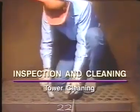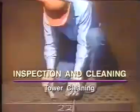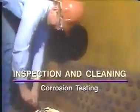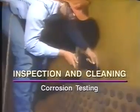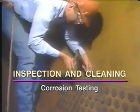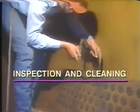Even after purging and water flooding, there are usually some stubborn deposits that remain in the column. These deposits are removed with special solvents or by manual scraping. After the tower has been thoroughly cleaned, it must be carefully checked for corrosion. We do this to make sure that all equipment is still strong enough for future use. A corrosion inspection is usually made by measuring and recording the thickness of various metal parts inside the column.